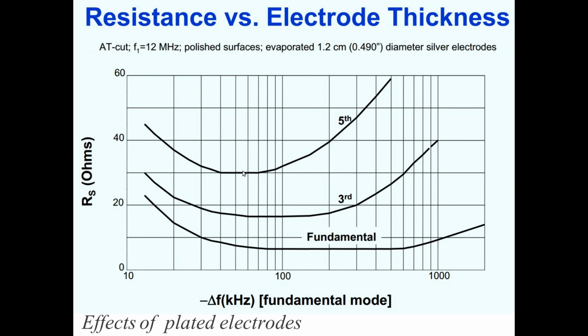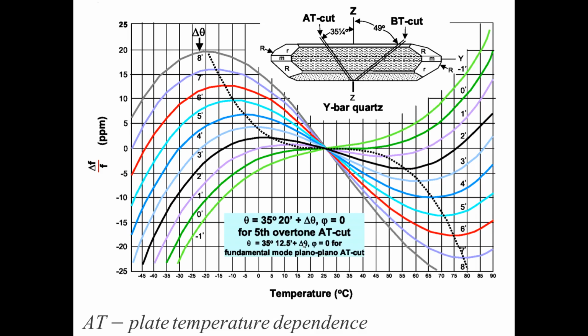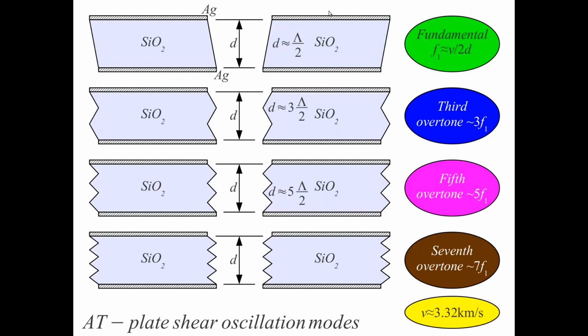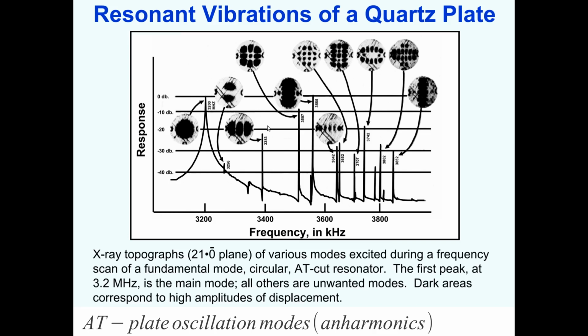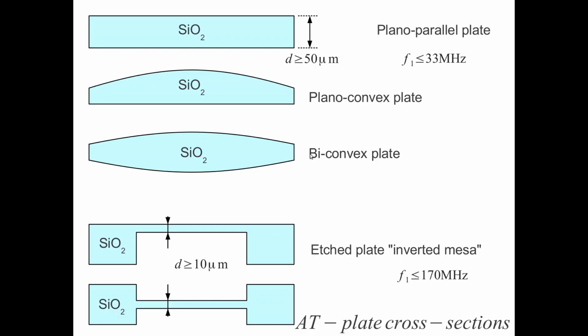So this is just to explain that there is a particular thickness of the electrodes that is ideal on this occasion here. Of course, any kind of dirt that accumulates on the quartz plate, so if dirt accumulates on these plates, it also kills the Q of the resonator. And in fact, many resonators can be repaired if they are not hermetically sealed. They can be repaired by washing them in an organic solvent to remove any dirt from the quartz plate, because dirt also kills the Q.